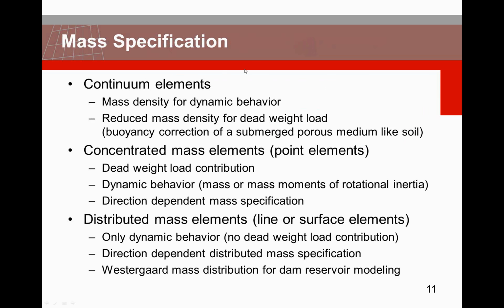The next thing we're going to talk about is the mass specification. How do you get this mass into your models? For continuum elements, probably the largest part of your model is just the mass density that you're going to have to specify. The mass density is being used for the dynamic behavior.